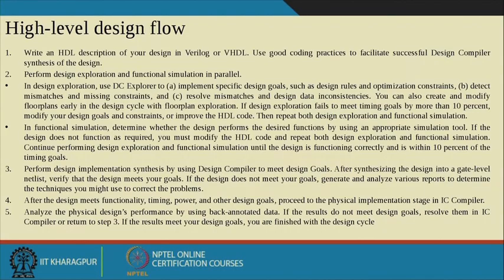Welcome back everyone. In the last lecture we saw what is needed: the RTL file, the corresponding library file, and the constraint file. These are the inputs to the design compiler, and there are several compilers like power compiler, library compiler, and HDL compiler. They compile all this information, and after compiling, it produces the corresponding gate level netlist for the input logical expression.